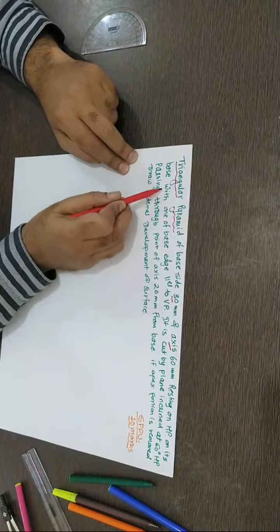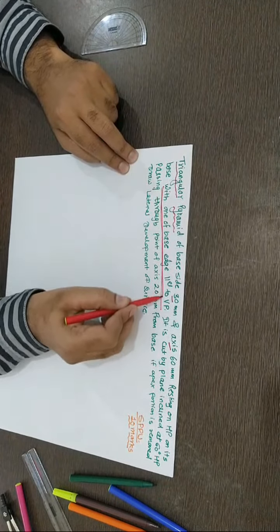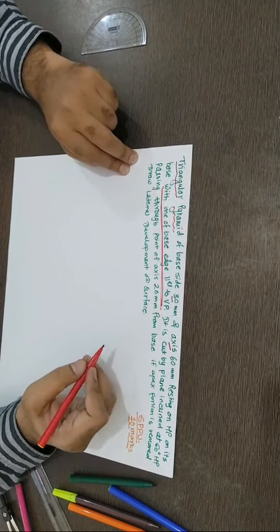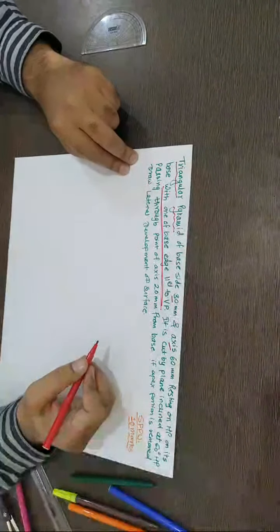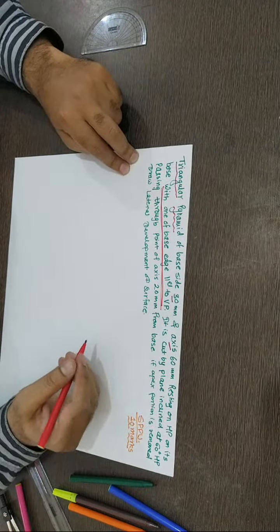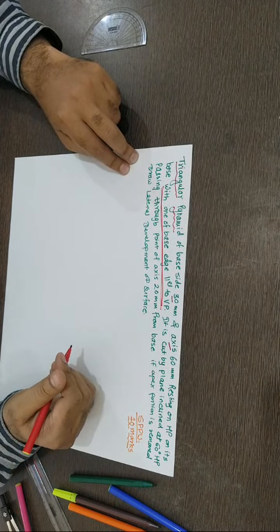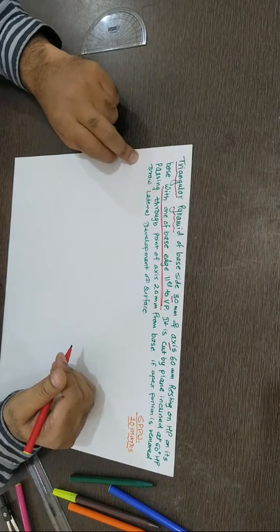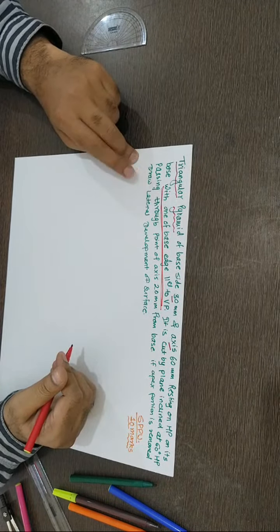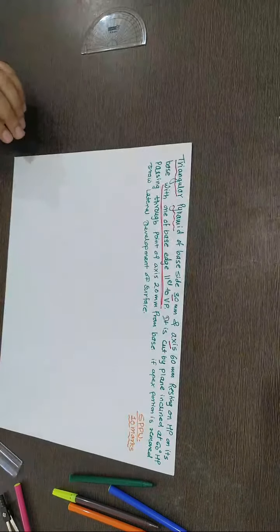Additional thing you should remember: if it is given, you should follow this condition for your solution. Otherwise, normally for a pyramid we always make sure one corner is towards the right so that we can get the true length in the front view. But now, as one of the base edges is parallel to VP, even though it is a triangular pyramid, let's see how you can draw this shape.